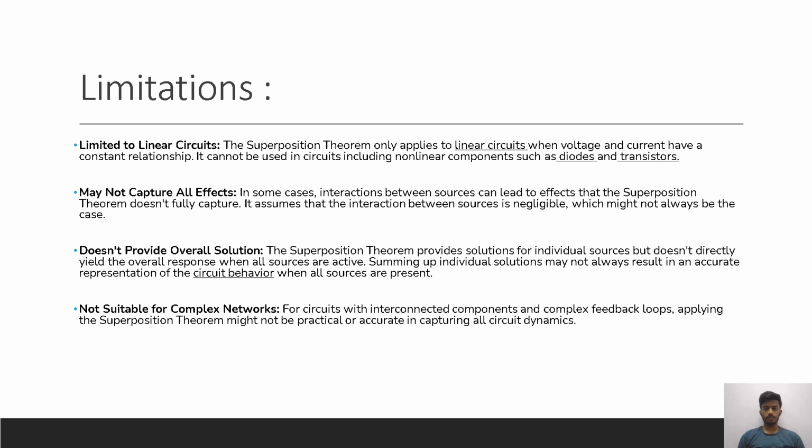Summing up individual solutions may not always result in an accurate representation of the circuit behavior when all sources are present. Not suitable for complex networks. For circuits with interconnected components and complex feedback loops, applying the superposition theorem might not be practical or accurate in capturing all circuit dynamics.